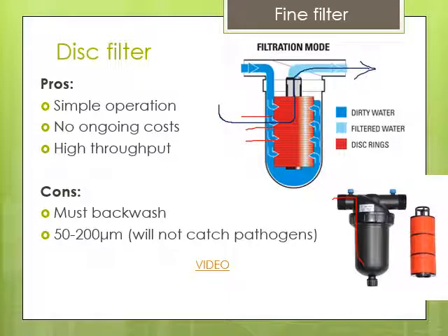And of course, debris will start to get caught in between the discs and plug them up. Eventually the water doesn't flow so well through the discs. So what the system does is it actually reverses the flow. Let me get my blue color. So the water comes in this way instead and shoots into the center and then shoots out the other way and knocks the debris out, and it goes through the entrance and is then diverted into waste.